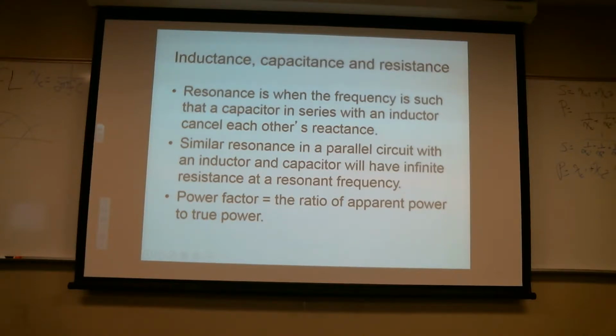The problem is if I change the frequency, it's going to mess a bunch of other stuff up. So rather than change the frequency, we're going to keep the frequency very fixed. And we're going to do our best to design the circuit to be resonant. So every time somebody turns an inductor on, we'll turn a capacitor on. Now, in truth, that in itself is also not entirely practical.